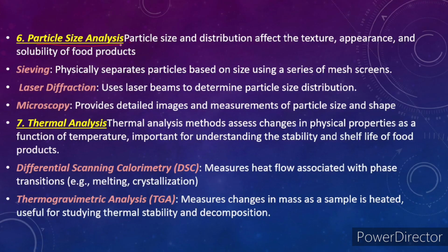Now coming to the particle size analysis, it also affects the texture, appearance and the solubility of the food products. In this, the sieving method is the using of mesh screens. It separates the particles based on size. Laser diffraction uses laser beams to determine the particle size distribution. Microscopy provides detailed images and measurements of the particle sizes and the shapes.